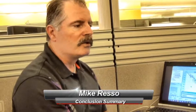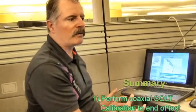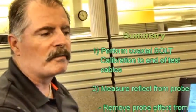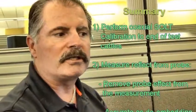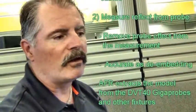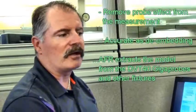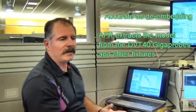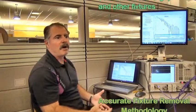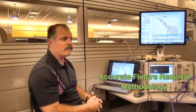And so, in conclusion, what we've shown is probing with a VNA and driving the automatic fixture removal technique with physical layer test system software, we're able to first do a coaxial calibration to the end of the test cables, and then by just simply looking at a reflect of the probe, we're able to remove all of the probe effect, which is just as accurate as de-embedding, because AFR allows us to extract the S4P information of the probe, which is the model. And so this is a very accurate methodology.